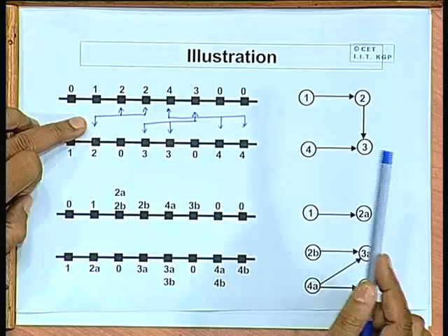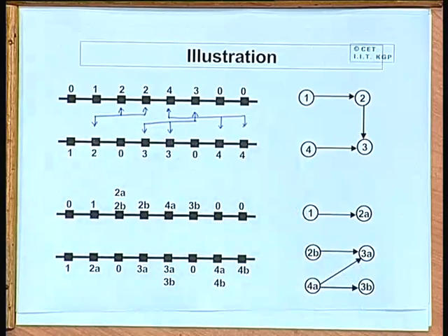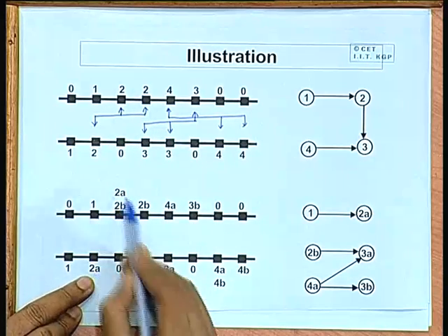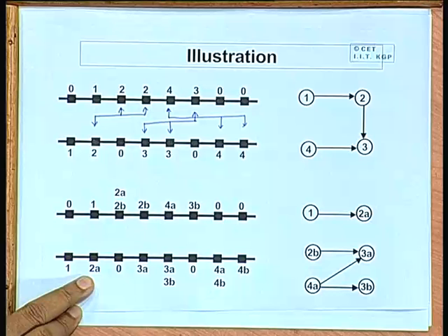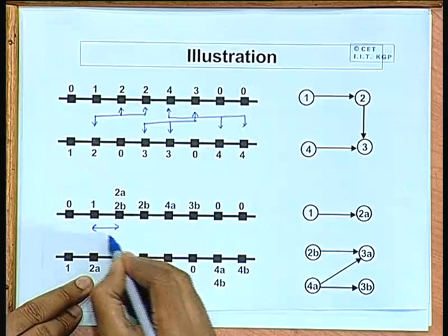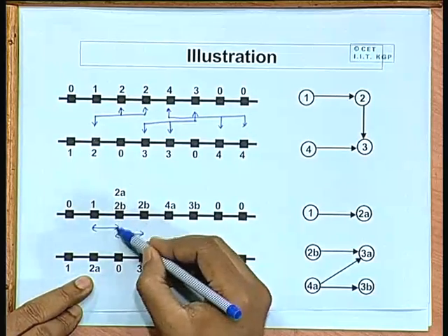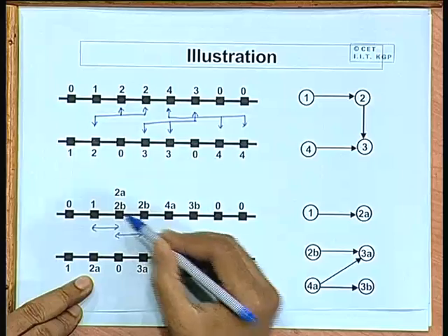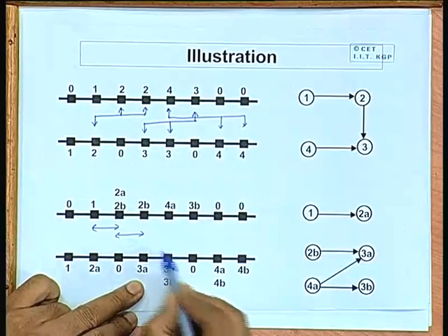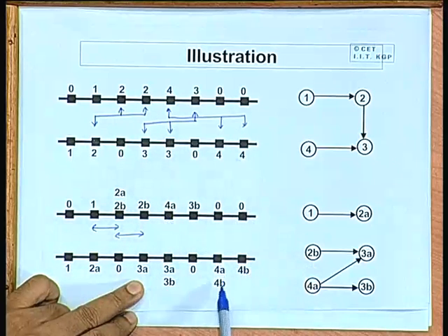So, as per our strategy, we break these nets up into individual 2 terminal nets, like net 2, 2 and 2 we break up into 2A, 2A and 2B, 2B. So, actually now there are 2 different nets, one is 2A like this, one is 2B like this. Of course, 2A and 2B touch at a terminal obviously. Similarly, net 3, 3A and 3A and 3B and 3B. Similarly, 4, 4A and 4A, 4B and 4B.